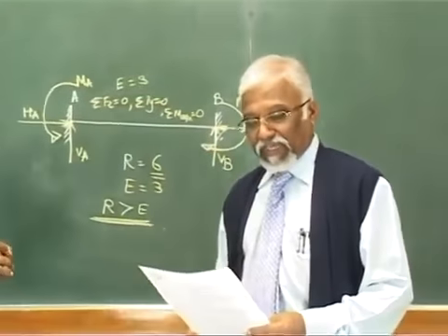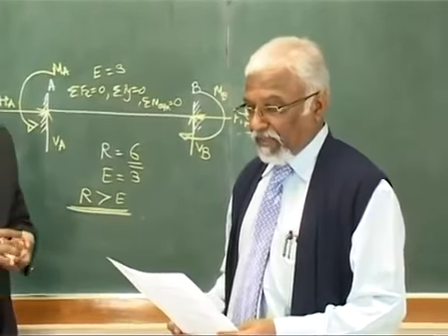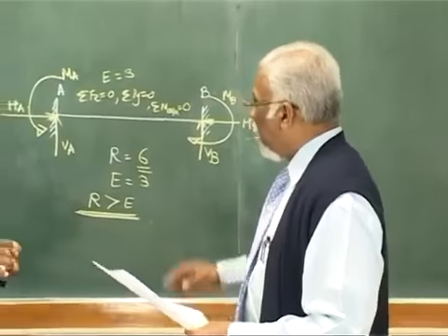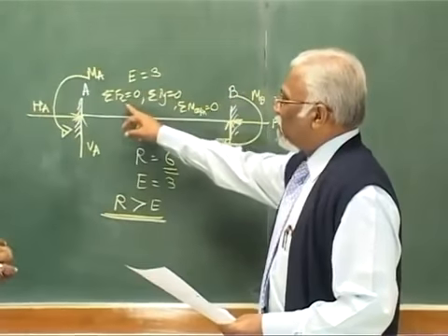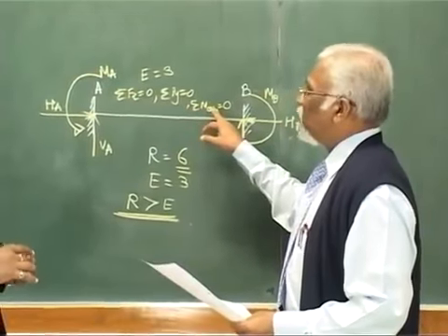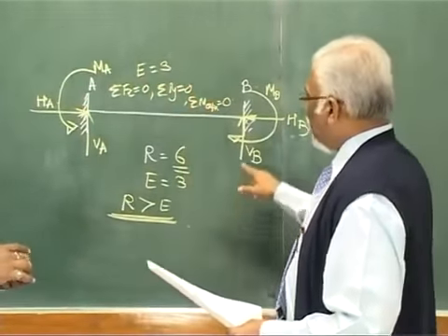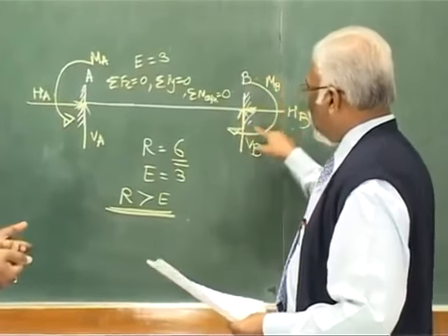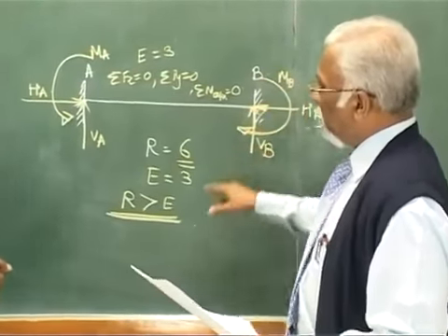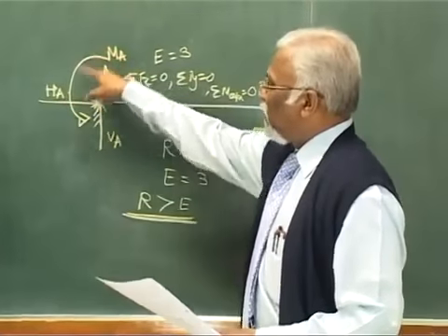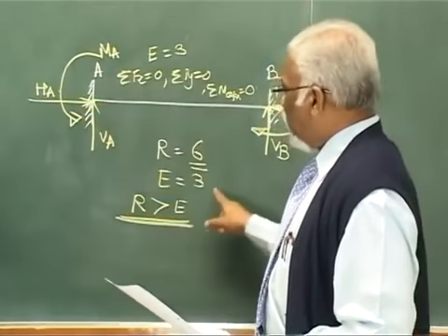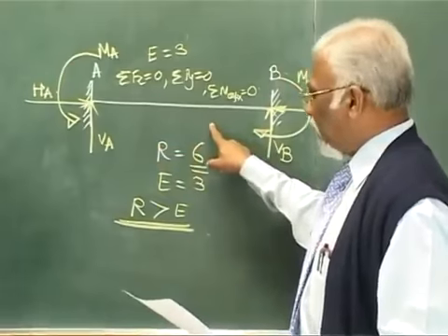So Raviraj, you would say that statically indeterminate beam is the correct answer. And you tried to explain that you had these 3 equations which need to be solved. So equations are 3. Reactions which you calculated are 1, 2, 3 on this at point B. Similarly 1, 2 and 3 at this side of beam. So you have total 6 reactions which are there.